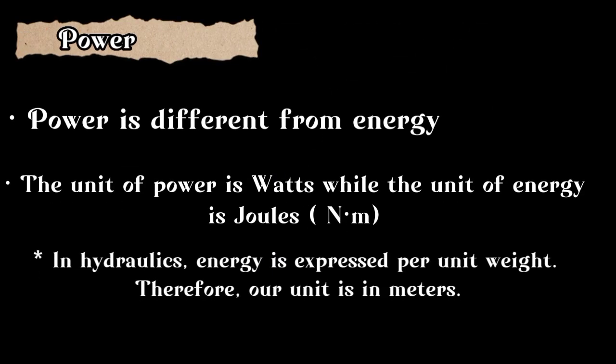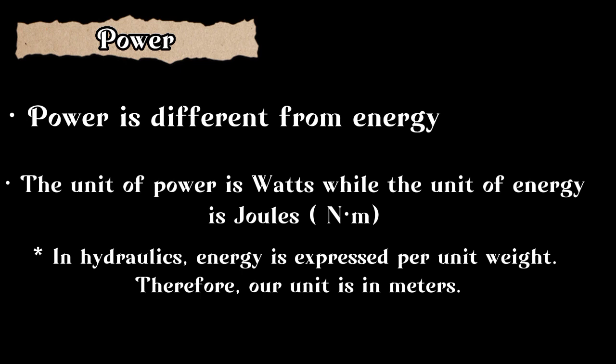Now let's talk about power. Power is different from energy. The unit of power is watts, while the unit of energy is joules, which is also Newton meter. In hydraulics, energy is expressed per unit weight. Therefore, our unit is in meters. That's why when we are solving Bernoulli's equation, our unit is meters, because we are dividing our energy by weight. If we divide Newton meter by weight, which is in Newton, what remains is meters.